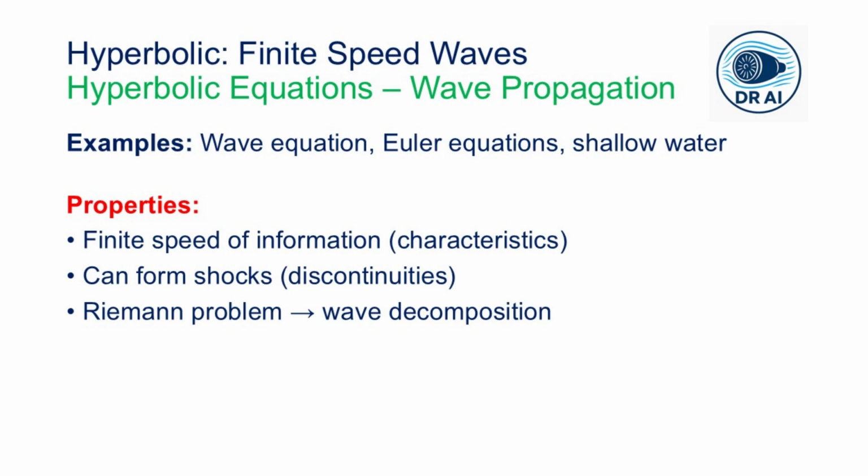So it is the key to understanding shock formation and the foundation of Godunov type methods in modern CFD. Along each characteristic, we define the Riemann invariants, combinations of physical quantities that remain constant along that characteristic. So using these invariants, we can predict the shock formation and propagation.